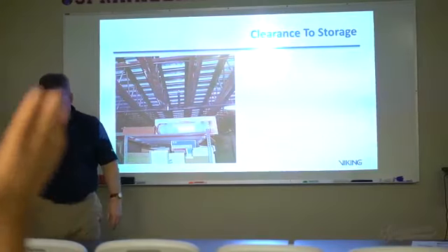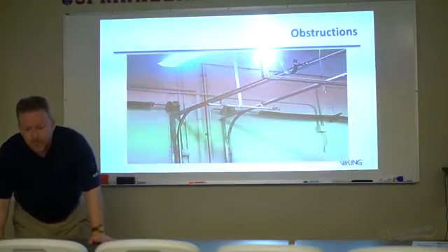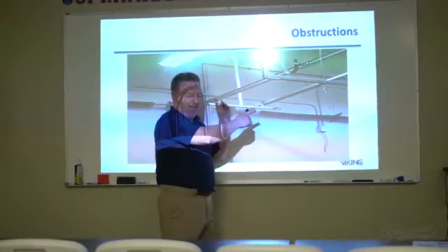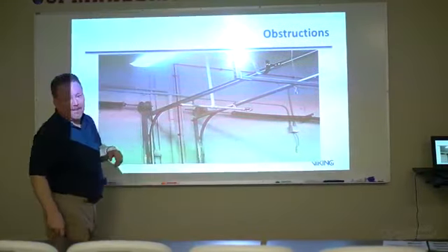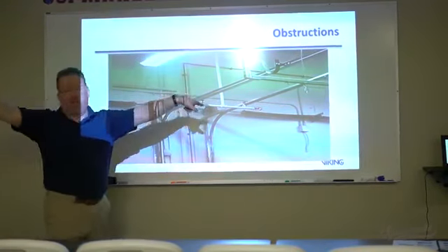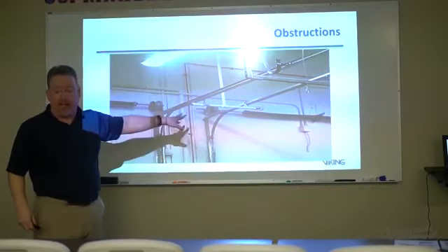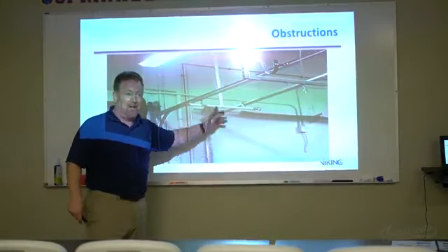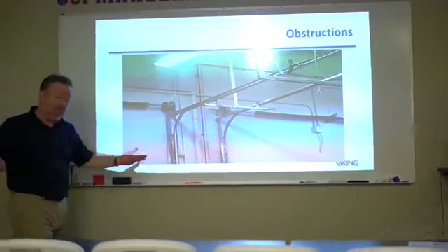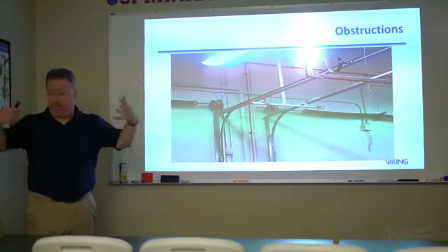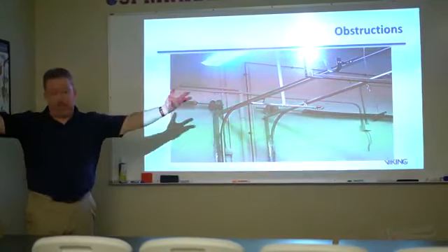Doesn't it matter if you have a closer sprinkler head, and the other one? You mean because these are so close? Yeah, these are sidewalls. Well, the best answer to that is these are sidewalls, so they're both spraying in opposite directions. One's not going to spray on the other. The big challenge might be if you get one that's real close to the bottom of one, you might get them both operating at the same time. But again, it's better than having none of them operate because you've got this big 10-foot obstruction. A false ceiling basically is what you've opened up to.